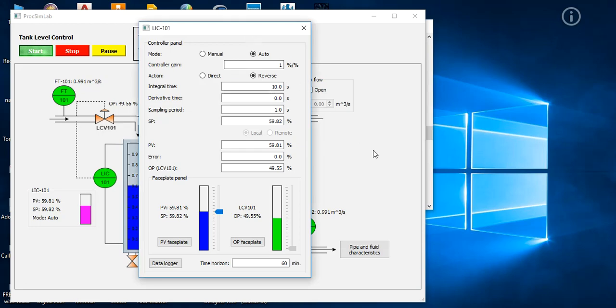Using control valve that is air to open, the controller is set in reverse action, meaning any positive deviation of process variable from setpoint will result in decreasing controller output, in this case less liquid flow into the tank. The PID controller gain and integral time are arbitrarily chosen, although the parameters can be properly tuned based on the dynamic characteristics of the process and control loop.